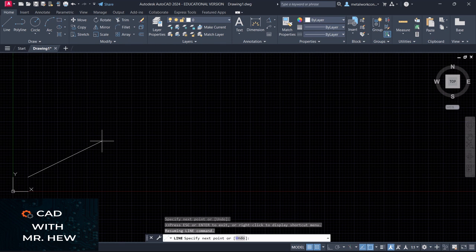So we're going to type 150 from the original axis where the x-axis meets the y-axis, right? Comma, and we're going up. That was 50, right? So it'd have to be about 100. Enter. There it is. Press enter. So that is by coordinates.